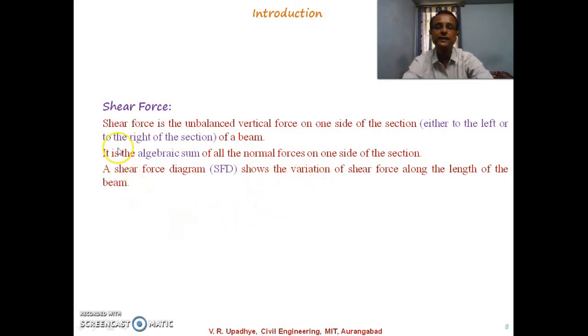So what we understand by shear force is the unbalanced vertical force on either left of a particular section or right of a particular section of that beam. And it is the algebraic sum of all the forces on that particular part. It may be the left part under analysis consideration.